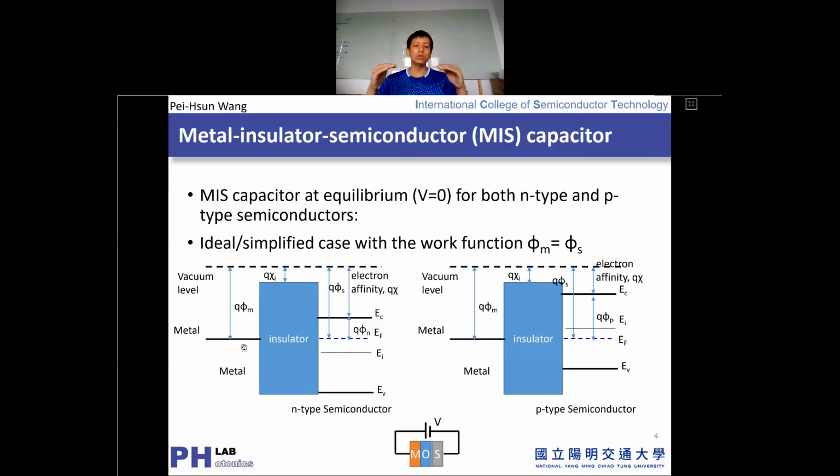So the Fermi level is initially aligned, just like we talked about for the p-n junction. If there is no additional external potential, the Fermi level will be flat on both p-type and n-type. Here it works the same way. We get the n-type semiconductor, and the metal aligned with the same Fermi level without external biasing. For this ideal case, since we assume the work functions are the same in the metal and the semiconductor, the Fermi levels will align perfectly without any band bending.